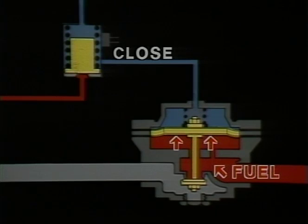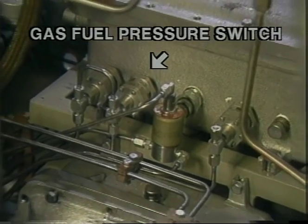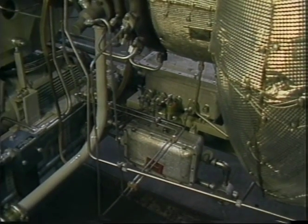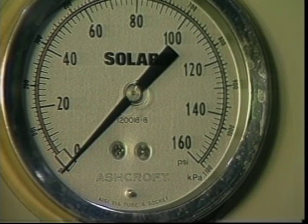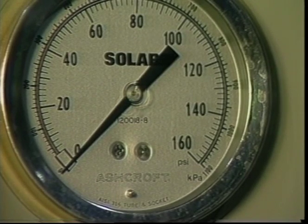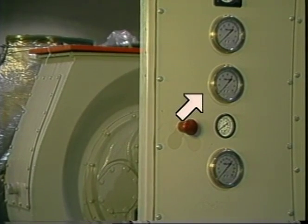Incoming gas fuel pressure is monitored at the gas fuel pressure switch. The switch located at the package junction box will prevent package startup or cause a shutdown if fuel pressure is outside of the preset limits. A pressure gauge continuously displays the pressure level in the fuel supply line. The gauge is mounted on the engine gauge panel at the forward end of the package.